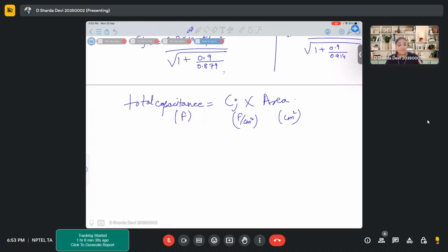First of all, when we are talking about junction capacitance and the transistor is in the saturation region, there is very high drain voltage. Your majority capacitance comes due to your drain voltage. So the majority capacitance that you see will be due to the reverse bias drain capacitance.